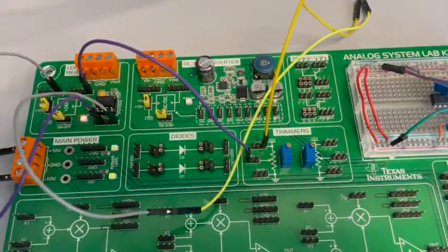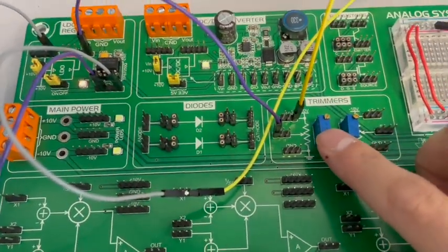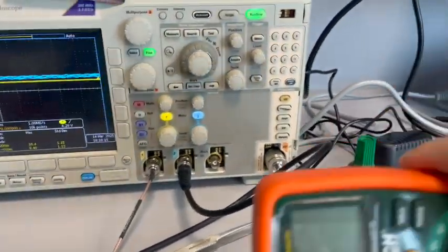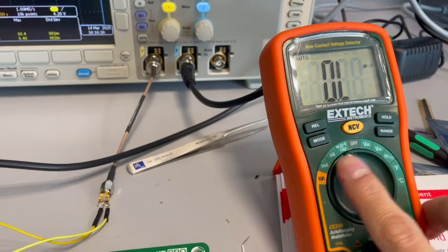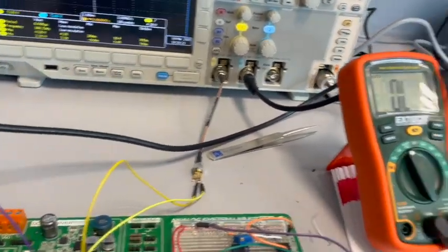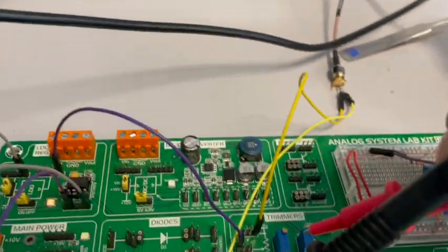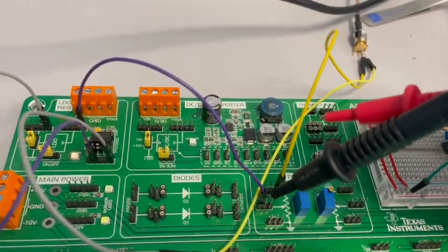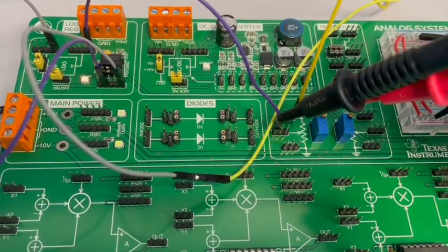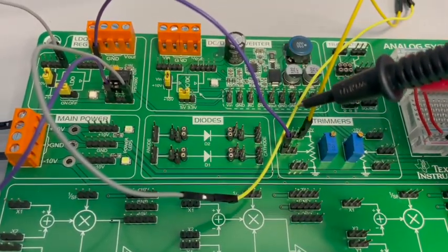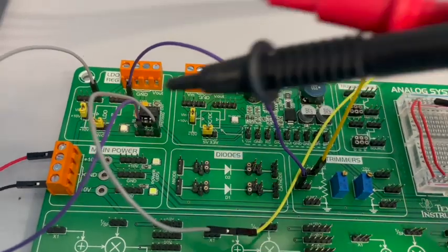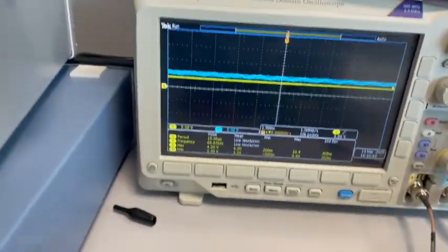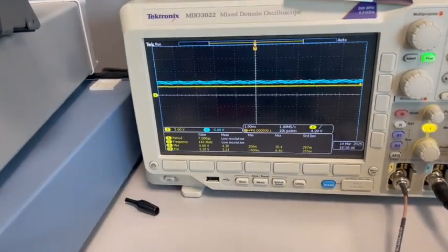One more point: in order to see how much resistance you have, you need to use the multimeter. It's pretty easy. You put your multimeter in ohm mode and measure the resistance across these two connectors. In the lab I'm gonna show how it's done. Every time you measure these trimmers, once you set 100, 200, 300 up to 1k ohm, connect this to the output of the LDO and measure the output. Okay, that's it.